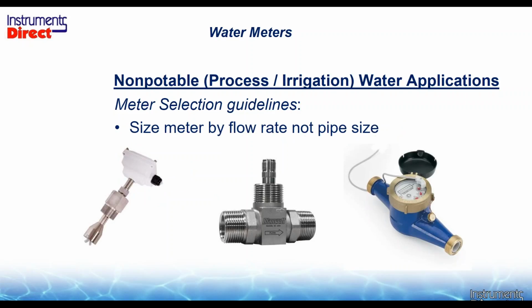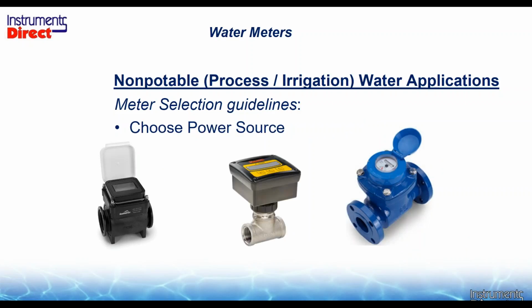Again, we need to size the meter by the flow rate, especially when we have a mechanical flow meter in there. For example, on a turbine flow meter there, some turbine flow meters need enough flow to make the turbine move, so they need higher flow rates. So in order to have higher flow rates, you may have a smaller line size there. So keep that in mind, very important rule.